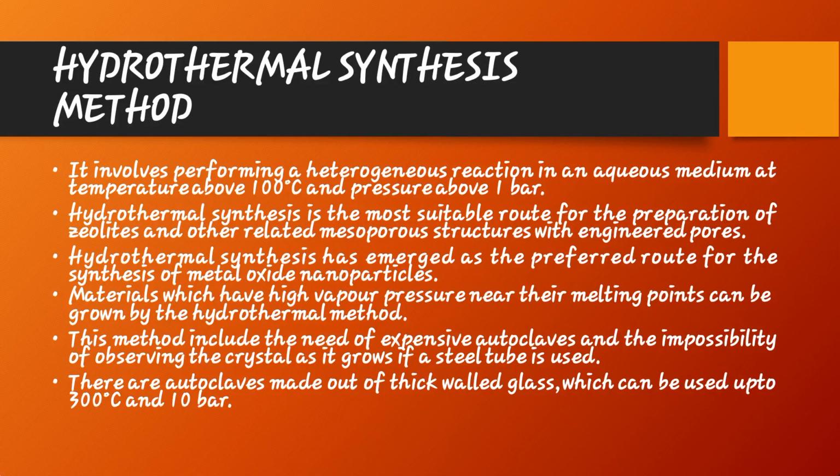Materials which have high vapor pressure near their melting points can be grown by the hydrothermal method. This method includes the need of expensive autoclaves and the impossibility of observing the crystal as it grows if a steel tube is used. There are autoclaves made out of thick walled glass which can be used up to 300 degrees Celsius and 10 bar.